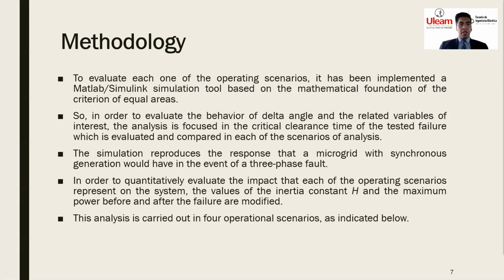In order to quantitatively evaluate the impact that each one of the operating scenarios represents on the system, the values of inertia constant H and the maximum power before and after the failure are modified. This analysis is carried out in 4 operational scenarios as indicated below.